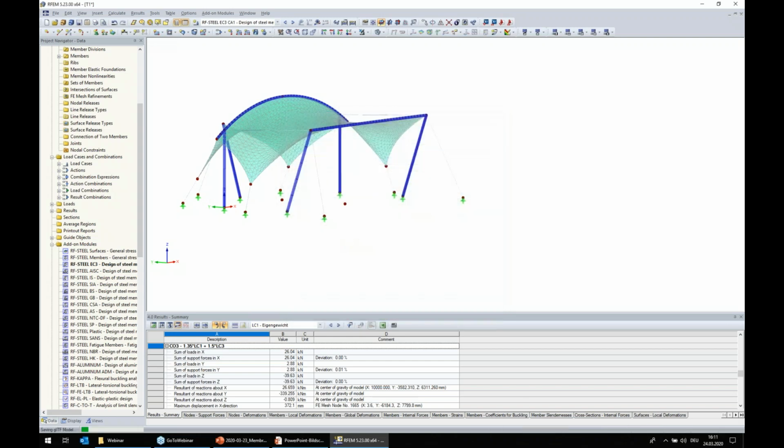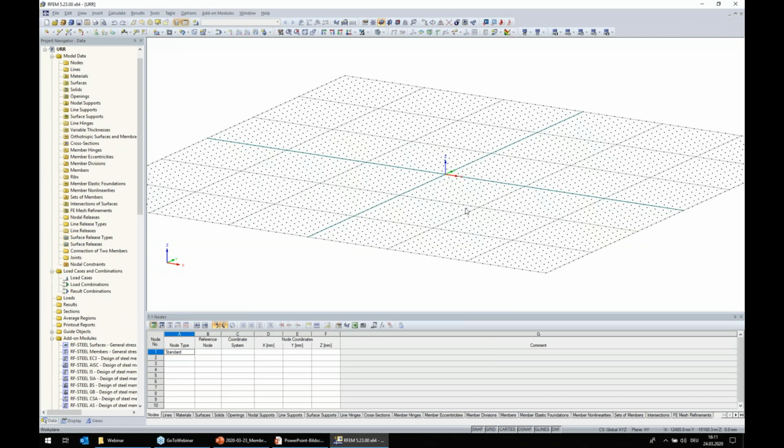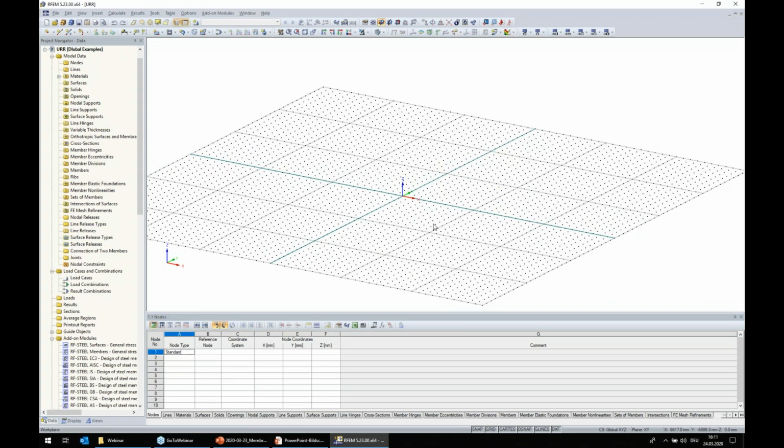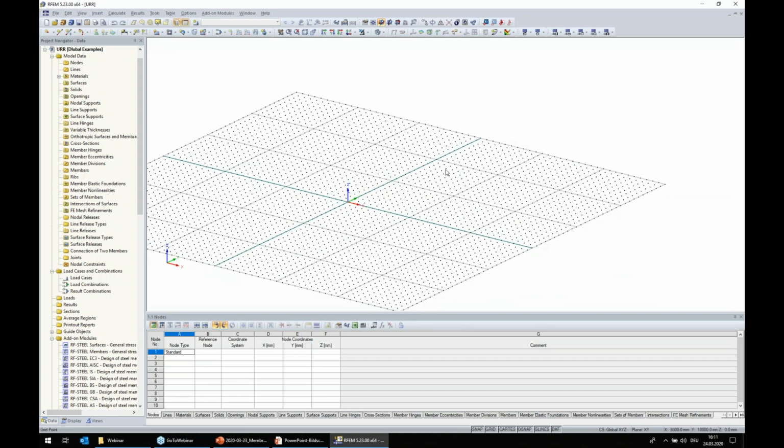So we open a new sheet, get an empty environment, and start modeling these additional bodies for the wind simulation. I know this seating construction has an available place of 20 by 10.3 meters with a height of 7.5 meters, so we can use this space.